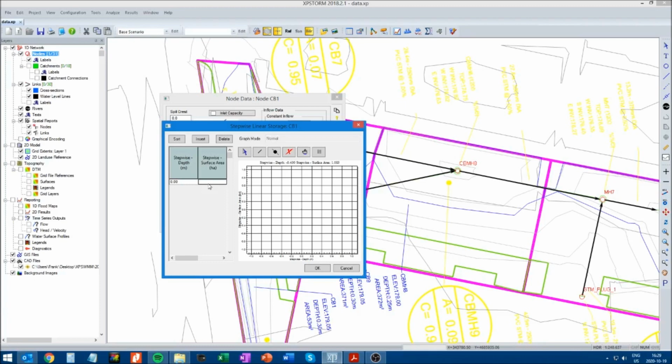So our catch basins are 600 millimeters by 600, so that's 0.6 times 0.6, and it has to be in hectares, so we have to divide that by 10,000. Okay, small number, could probably make it 0. So regardless, we'll put in the actual number. So that's 0.00036.